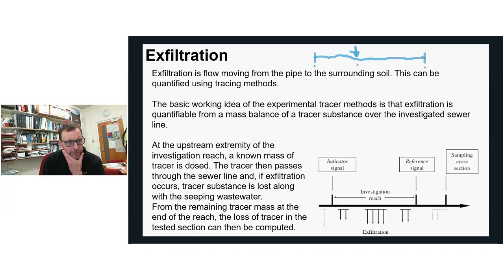Now, if we have the same setup, but this time we've got exfiltration, so the water's leaving the sewer. We've got a known dye concentration on the left. Flow is leaving the sewer, but when we measure the dye concentration on the right, the concentration is still the same.